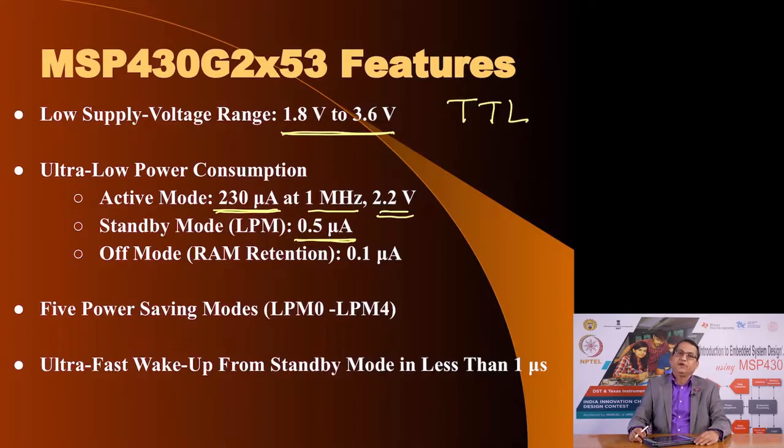And you can imagine that if you have a coin cell or a button cell, even on a single button cell, for how long this microcontroller can continue to operate, provided it has large periods of time when it is in a standby mode, but once in a while it could wake up and do real work and then go back to the standby mode. If you want to turn the internal operations off and just retain the contents of the RAM, then the power consumption will go down to 100 nanoamperes, that is 0.1 microampere, that is a really low current.